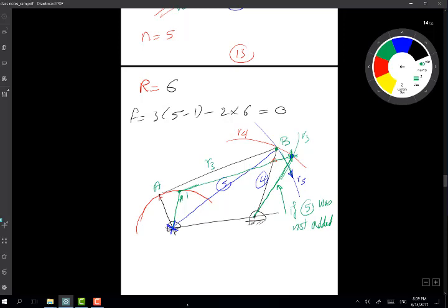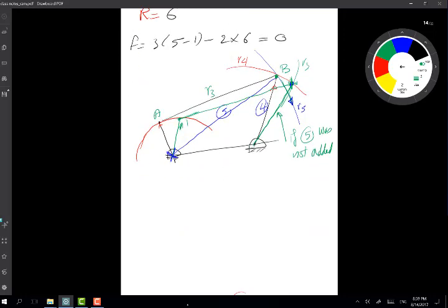So they will never really agree together, unless you have some elasticity in the system, like if link number 5 would be a spring or something like that, right? So that its length could change. But because we have rigid links, we know that the motion is not possible, and as such, we end up with a structure. So motion is not going to occur at all. So that's a 0 degree of freedom linkage, which has become a structure because it's 0 degrees of freedom, right? And it makes sense.